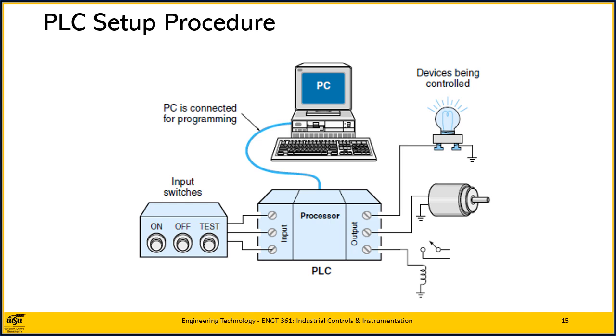In either case, the PC screen becomes a window into the workings of the program. If a problem becomes apparent, the program can be corrected immediately, and the testing continued until all bugs are worked out. When the testing is complete, the PC can be disconnected and the PLC will continue to execute its stored program as an independent unit.